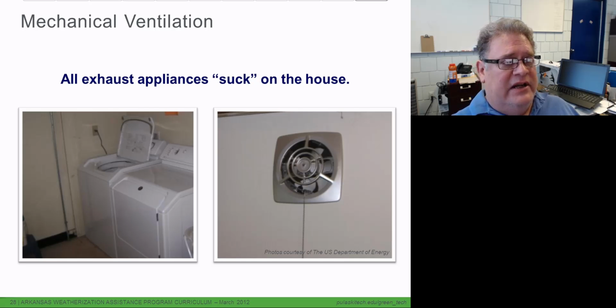Exhaust appliances. Now we're getting into our mechanicals. Dryers are exhaust appliances. Keep that in mind. Always keep that in mind. Even electric dryers take air from inside and pump it to the outside. They fill it full of moisture and then pump it out. We want it to go outside. That's some of the price that we pay.